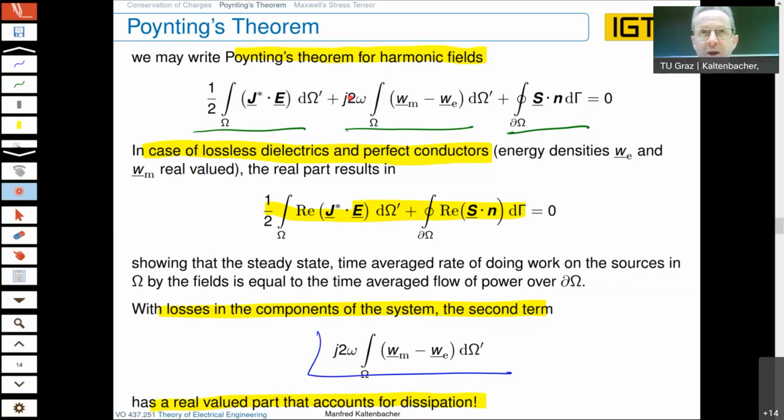There is always a problem in measurement technology. You want to get the hysteresis losses, but the setup you are using are sensing coils, and so you need a magnetic field which is changing over time. But when you have a magnetic field changing over time and you have a conductive body, also our ferromagnetic materials, like the steel sheets in transformers, have some conductivity. So you induce some eddy currents. The question is how you can separate the eddy current losses from the pure hysteresis losses.